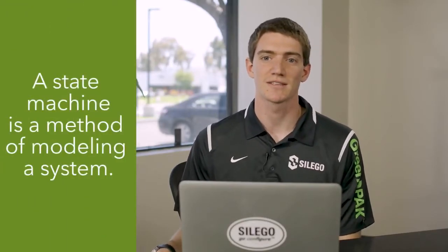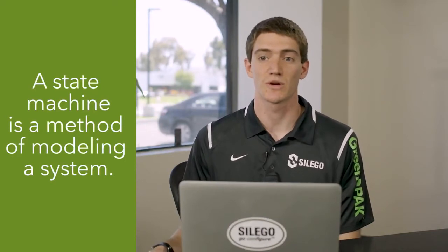In this video, we're going to look at GreenPAK's 8-state asynchronous state machine, or ASM. But first, what is a state machine? A state machine is a method of modeling a system that acts in one way or another depending on what state it is and what input it receives.